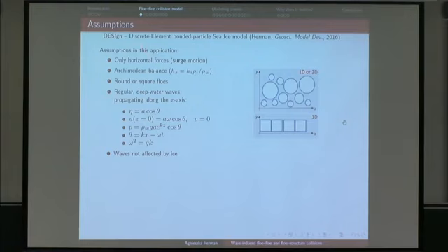These are the assumptions. What I model are only horizontal motions of ice floes, so it is a model of surge motion. And in the vertical, we simply assume that all the time the ice is in Archimedean balance. This allows us to simply calculate the submerged surface area and volume to estimate the forces acting on the ice. And in most cases, I used round floes in order to compare the results with this lab test that you have just seen.